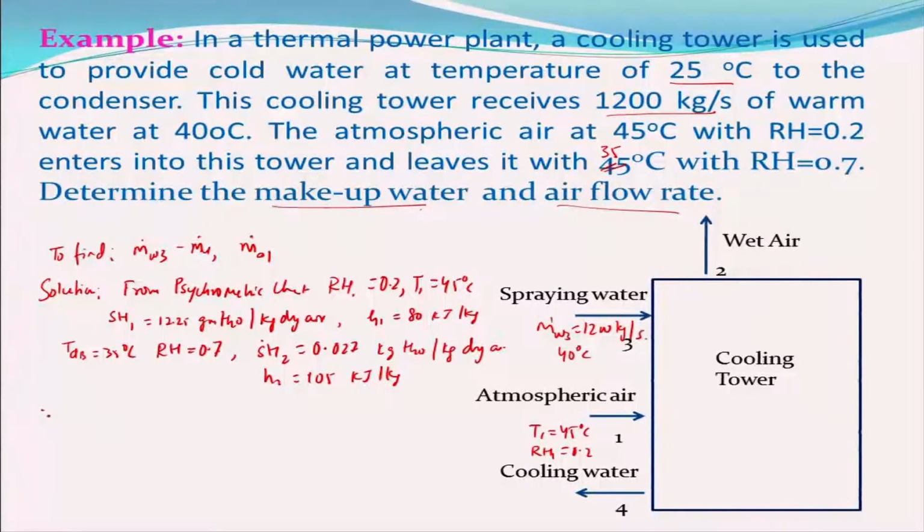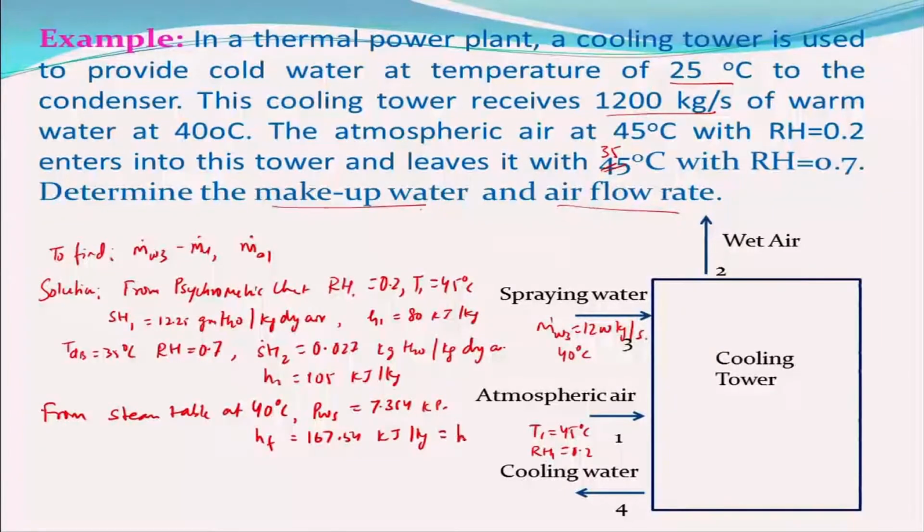And from the steam table at 40 degrees Celsius I can get PWS equal to 7.384 kilopascal, HF 167.54 kilojoule per kg, which is nothing but your H3.